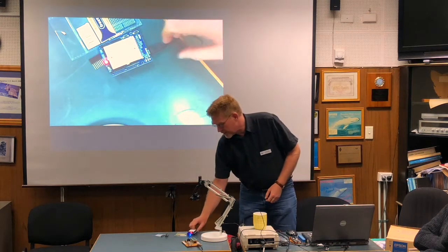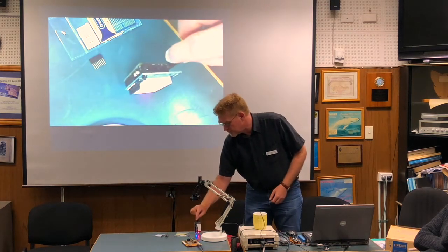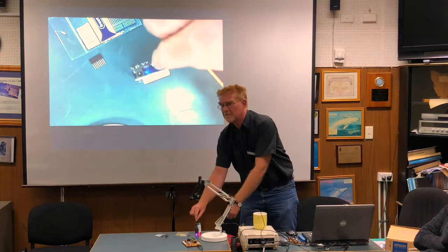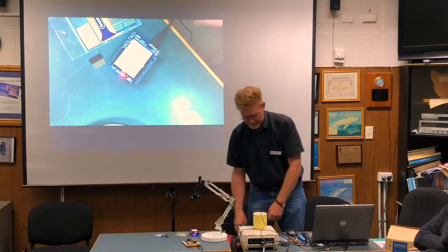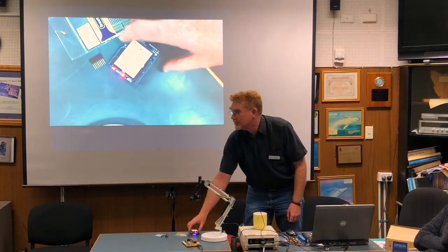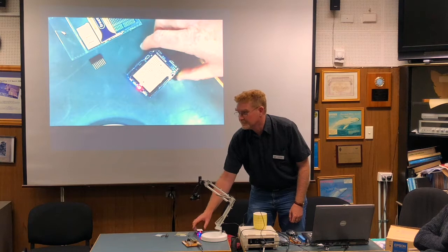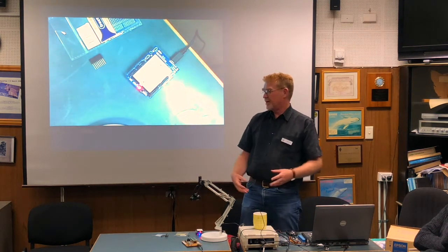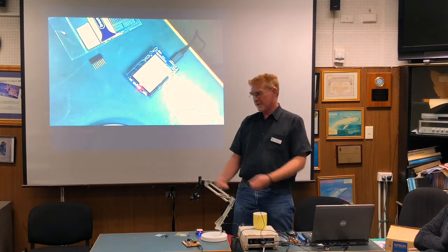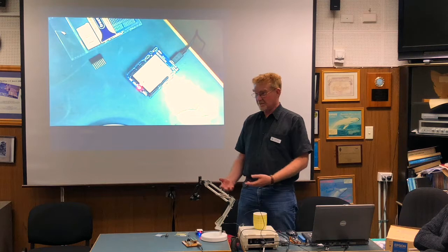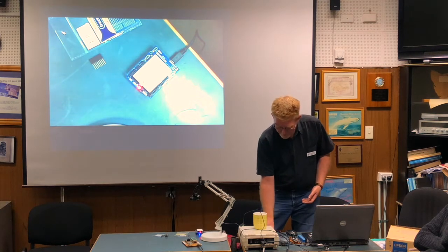I've found it's generally better, if you're going to do something with shields, to use a DC input socket and the external power supply, and avoid giving your computer a hard time. It's a lot harder to fix and repair. So you can have both plugged in at the same time, the USB and the DC. And there are, of course, as you'd expect, people with shields with batteries and chargers, so you can charge it on your PC and take it away hands-free. Fifteen years gives people a lot of ideas for doing these kinds of things, and they're kind of popular.